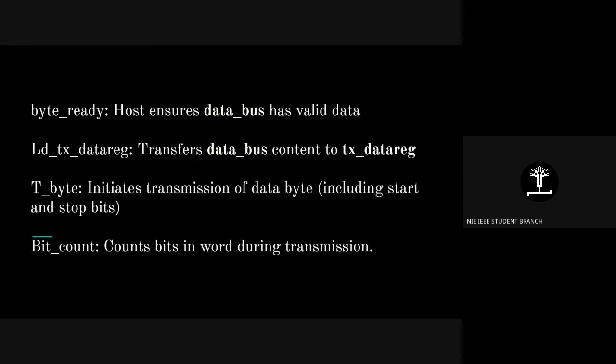How does it provide? You have to first instantiate. All registers are inputs again, and wires are outputs from here. Call it transmitter. Call it UUT. Call it Skanda. Call it Hippo. Up to you. And then you have to wire it up.